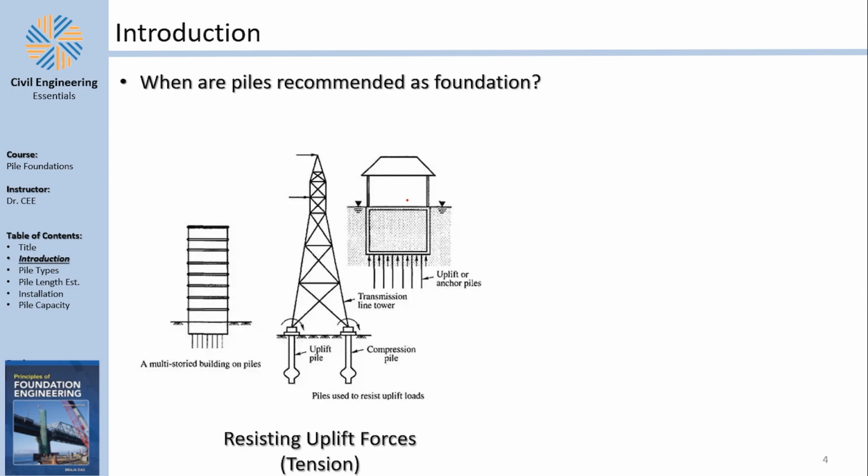In other words, piles would resist the upward and downward movement of soil, reducing the amount of cracks you would have here. The next case is when you have tension on the soil or uplift, meaning that there is a tendency of an element in the structure to move up. This could happen due to horizontal forces or earthquake forces, where you apply horizontal forces which will be resisted by a couple force of compression and tension at the pile. This will cause uplift forces or tension forces on the element. It wants to be rooted up basically. And of course, soil cannot hold any tensile forces, so you need to resist this with a pile. You would think, wait a minute, how can a pile provide tensile forces? Well, due to skin friction, at least.